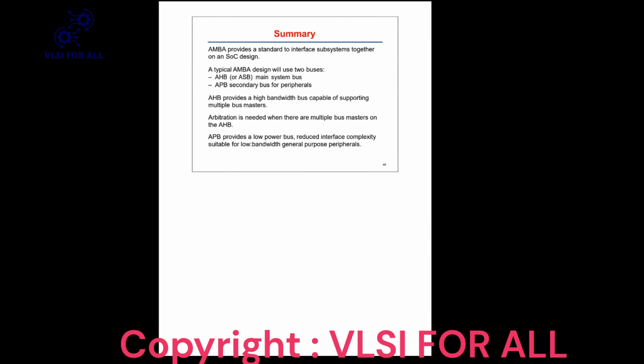So let's say it takes 6 clock cycles and APB handles just three transactions, but 5 transactions have been driven overall. How many transactions reach the APB? Only three. Two transactions are lost, because APB is not as efficient as AHB. AHB is working on a single clock cycle, but APB is working on 2 clock cycles. So to make sure our data is not lost, we require a bridge in between.